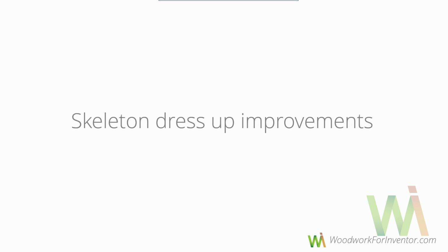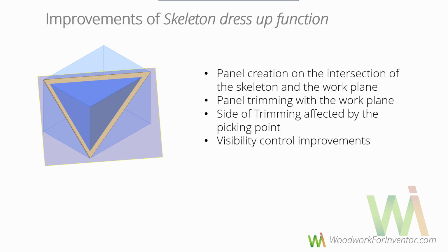And now let's move to the next point about the Skeleton DressUp improvements. As you know, this is a great tool which simplifies the design process and allows you to make a lot of routine operations quickly. So let's see what we have here. First of all, our customer requested the functionality to create panels on the intersection of the skeleton and the work plane. So now you can do this.